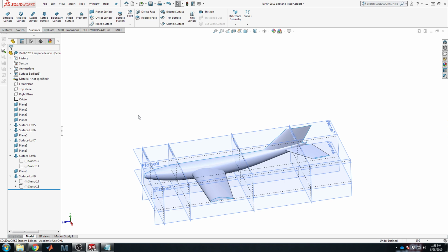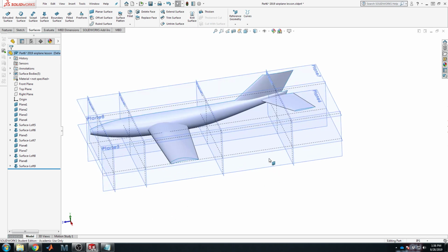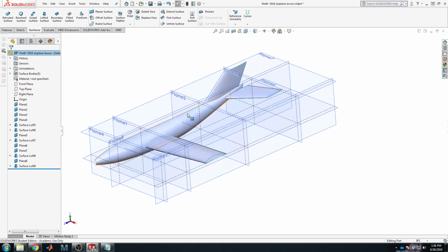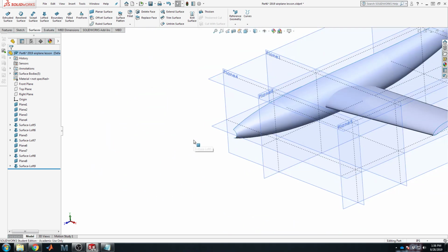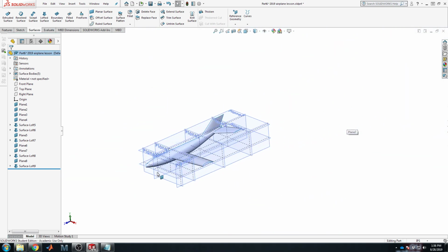You can obviously see how these elements can be moved forward, backwards, swept, give it dihedral. Basically just defining airfoil cross sections at different points and doing a loft between them to make nice linearly interpolated airfoil sections, or wing sections I should say. Easy enough, and of course the last thing you'd want to do here, if we're going to create an actual sealed outer mold line, which I guess my nose disappeared, but that's okay, we can do that later.